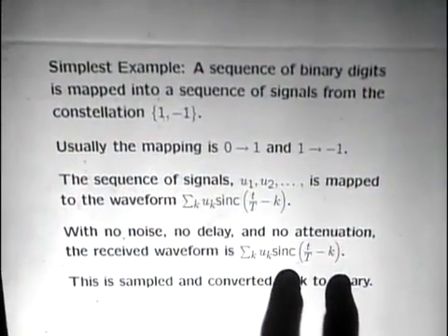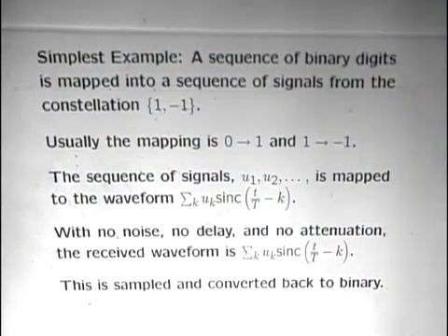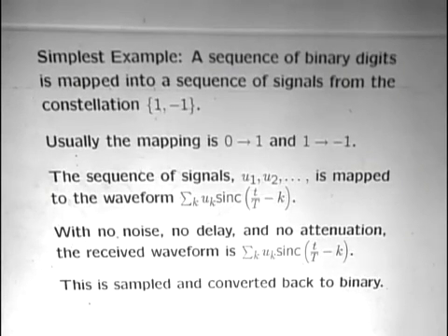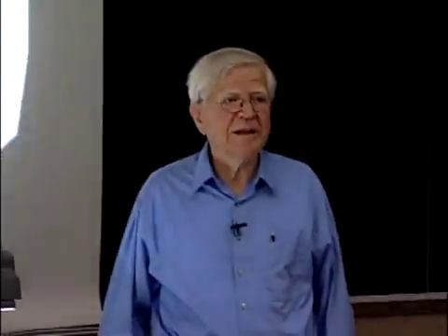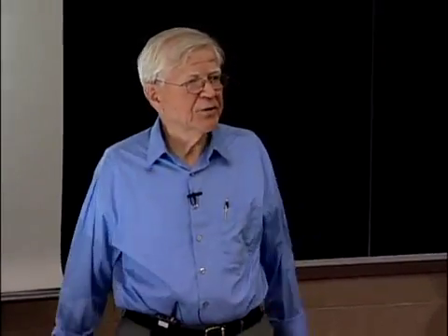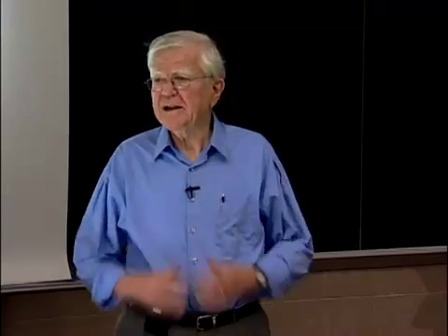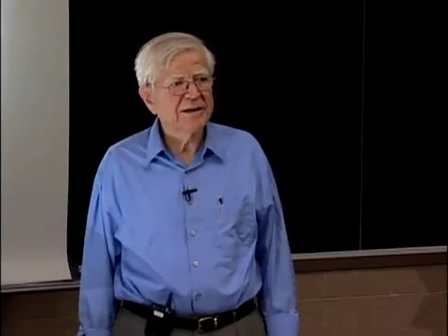you can't implement these even with the receiver timing different than the transmitter timing. But you can always approximate things with enough delay between transmitter and receiver so that you can approximate any filter you want to without worrying about causality at all. And it's hard enough designing good filters without worrying about causality that you don't want to bring that into your picture at the beginning. So communication engineers usually say that those timing issues are not important and a little bit of delay is not going to hurt anything.